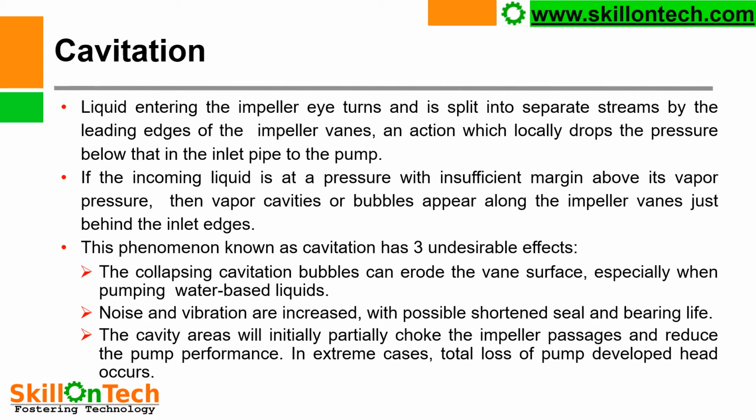The collapsing cavitation bubbles can erode the vane surface, especially when pumping water-based liquids. Noise and vibrations are very high, with possible shortened seal and bearing life. The cavity areas will initially partially choke the impeller passages and reduce the pump performance. In extreme cases, total loss of pump developed head occurs.